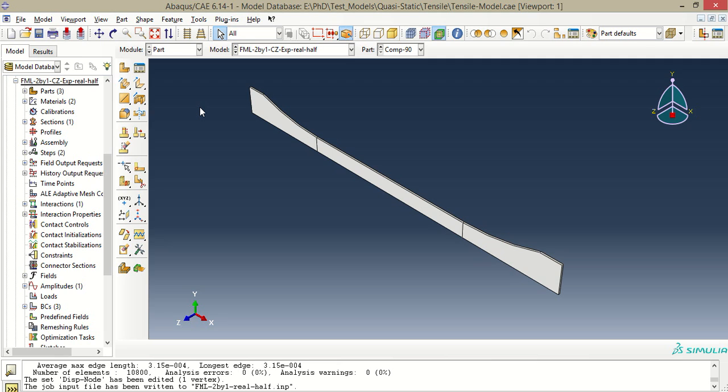In that case, a cohesive elements methodology can be used perhaps. I'll explain more on that when we get to it. For now, Abaqus CAE consists of different modules, as you can see, and we will be generating our model through these different modules. First is the part module, where we create the geometry of the product.